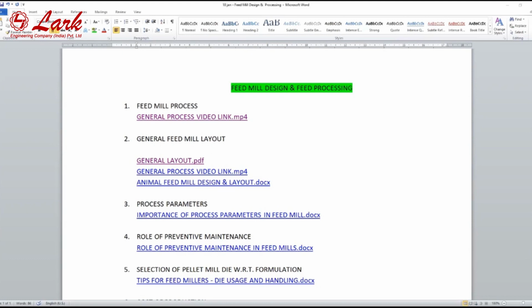In general practice, with respect to the prefab cost and the cost of the warehouse, 80, 90 and 100 feet is the ideal width of the warehouse with respect to cost and installation. After 100 feet, we have to put extra supports in the truss of the feed mill warehouse, and we may also have to add a center column for support.